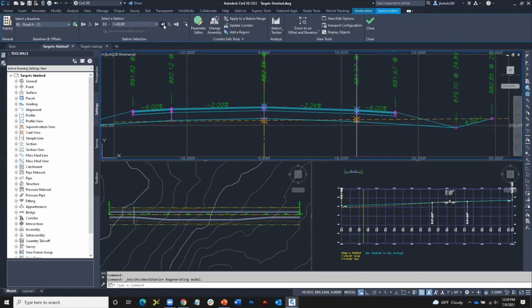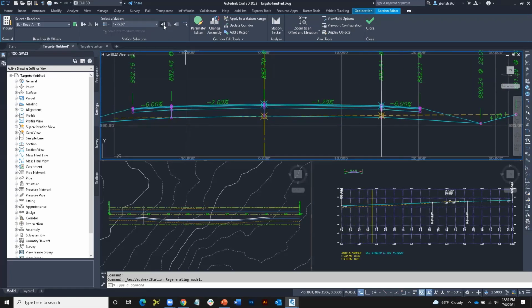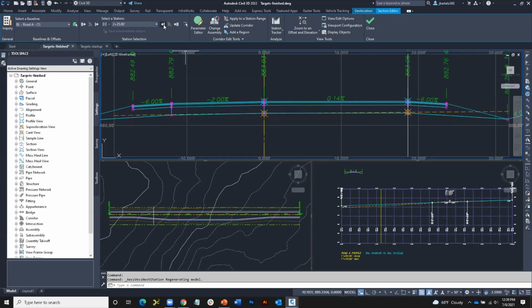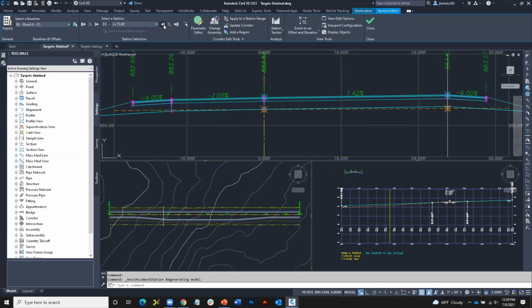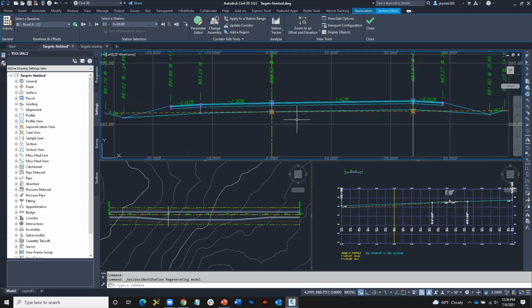As I step through my sections, not only can I see that that lane is following that alignment from its width, for its width property, I can see that it's getting its elevation from that profile. Okay, very, very easy looking at this, a very visual approach, graphical approach. It allows me to see my targets and potential targets in context with my design.